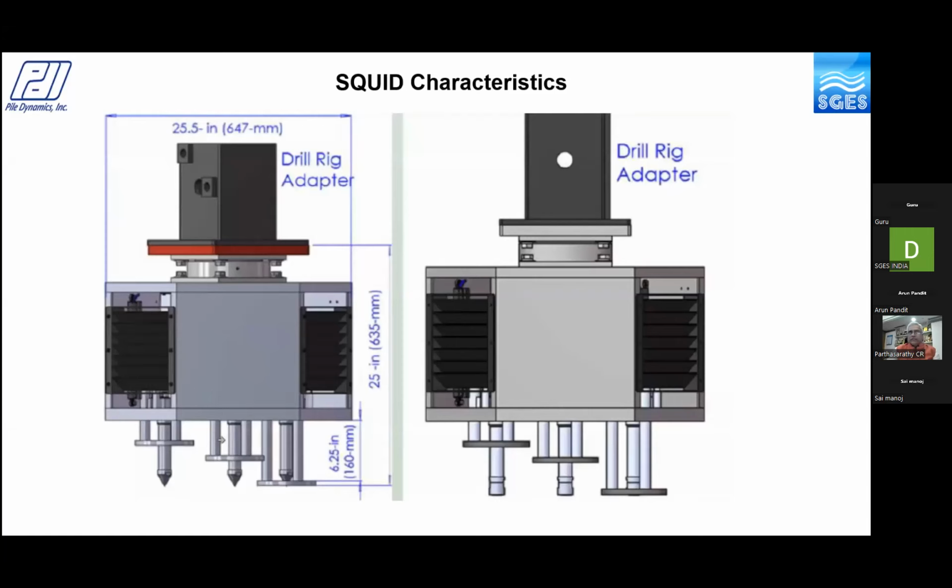If the thickness is more than the recommended thickness from some of the guidelines, during the load carrying, the pile will experience large settlements, and thus it will not carry the requisite load. And therefore, it is important to quantitatively estimate the thickness of contamination so that one could resort to some cleaning process before pouring the concrete.